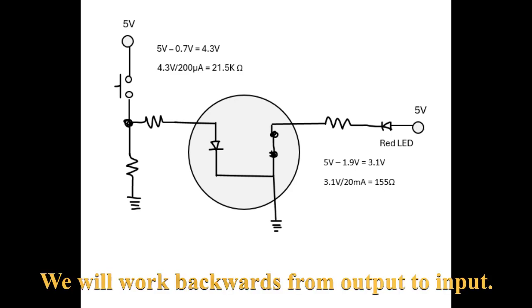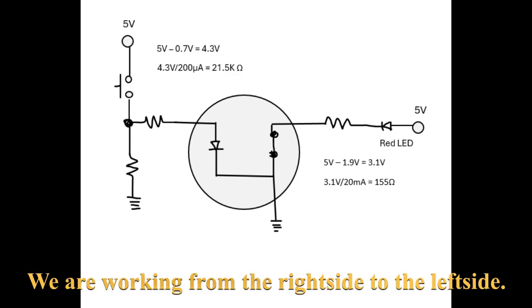You'll need to supply the output with the correct power supply, then subtract the voltage needed from the source to power the new device. Then the difference will be the voltage drop across the unknown resistor. Now, depending on the max current your device needs, you calculate the required resistance.